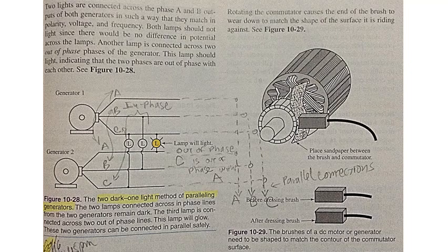Bearings should be lubricated on a regular schedule, as indicated in the owner's manual. Some bearings are permanently sealed and require no lubrication. If brushes and bearings are properly maintained, an electrical generator can easily provide more than 20 years of service.